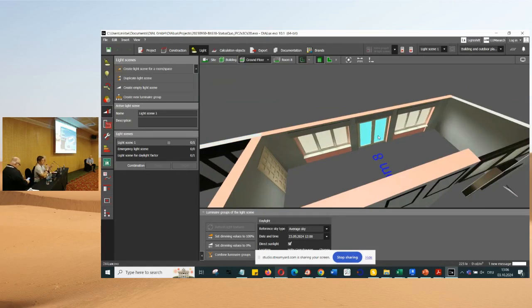Because they were designed in such a way that we have layers, we have an insulation layer, we have flooring, like IfcCovering, predefined type flooring, and unfortunately not every software is capable of reading that. So in my use case for daylight analysis, I need IfcSlab, IfcRoof, and not IfcCovering, predefined type roofing, and some other cases. So this is important to know.